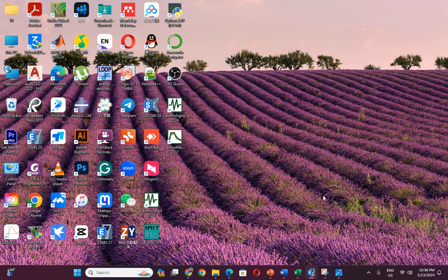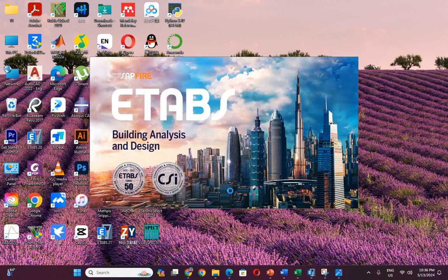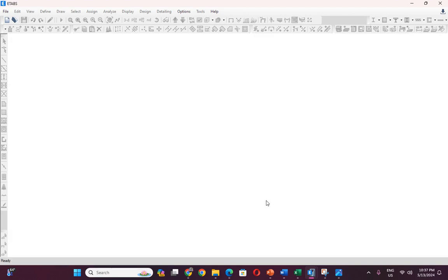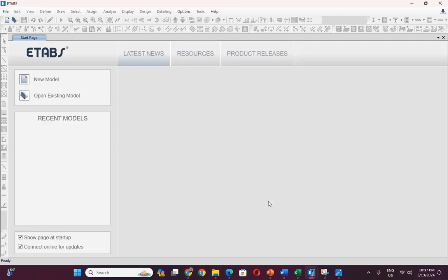I'm Osama Aslam. Today we are going to discuss non-linear dynamic analysis, time history analysis, and non-linear static pushover analysis. So let's open ETABS. I will design a four-story building according to the building code of Pakistan, because Pakistanis mostly follow the American codes. ETABS doesn't have the Pakistani code available in it, but we can input the response spectrum of the Pakistani code in that, and then we can compare the results.